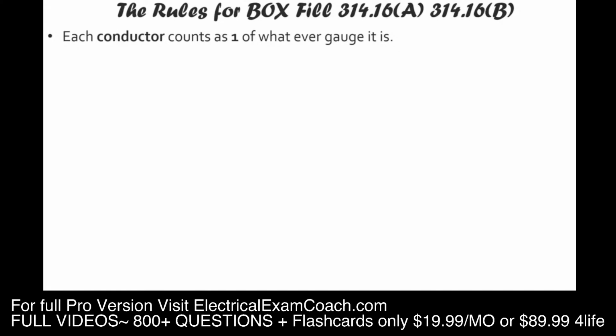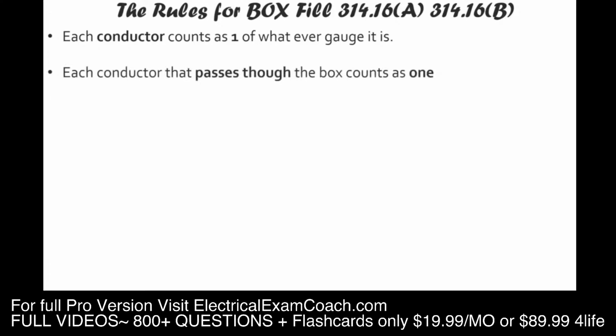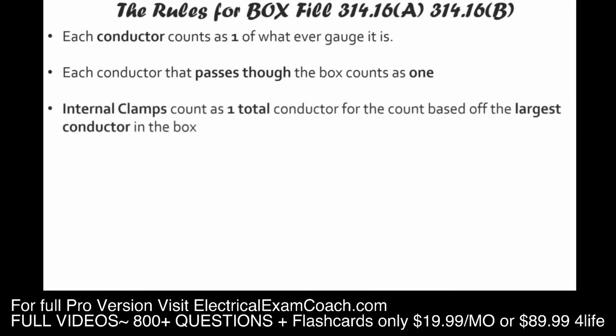So each 12 counts as 1, each 10 counts as 1, whatever gauge wire it is. Each conductor that passes through the box counts as 1. So even if it doesn't terminate or splice inside that box, if it's passing through that box, it counts as 1 each. Each internal clamp only counts as 1 total based off the largest conductor that's in the box.